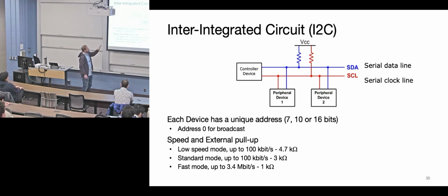The idea here is that you have to have these resistors to pull up. Remember that your microcontrollers, the STM32s, have internal resistors, so you can add pull-ups on the chip. So if you forgot to put them on your board, or just didn't want to solder them on that day, you could, in software, enable those resistors to go high. That's a nice feature.